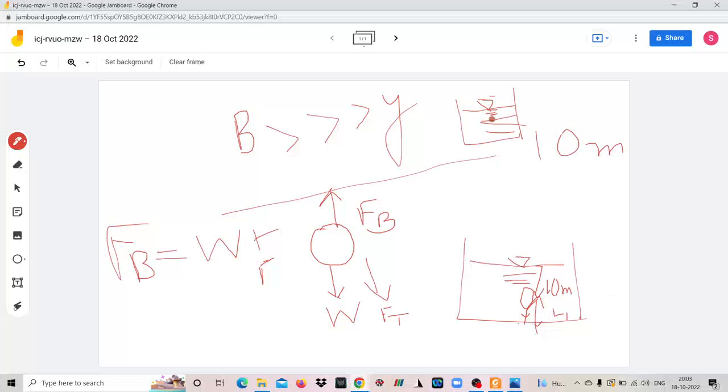Now when you are putting the balloon here, ideally speaking what you are telling is fine, that you have to take the weight of the fluid that is above the balloon. But when you are calculating the buoyant force, just think carefully: don't you think the effect of that overburden is already taken into account?